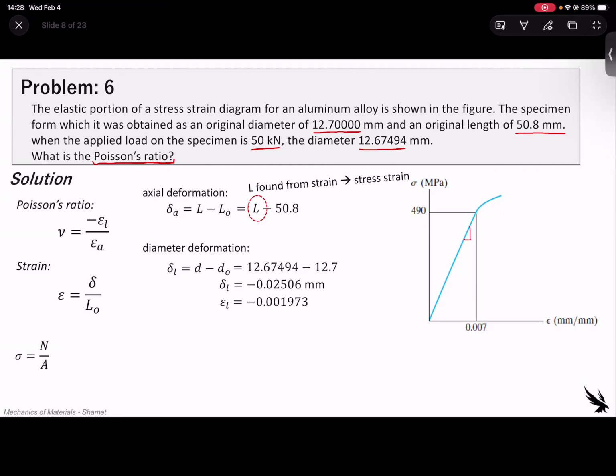And we know that the stress on this y-axis is the internal force divided by the cross-sectional area. We're told that the internal force is 50 kilonewtons. So 50 kilonewtons, or 50,000 newtons, divided by the cross-sectional area is producing a stress of this crazy looking number. We're just going to simplify this to 394.7 megapascals. Now, why megapascals? Because that's what this is currently showing in. So we know that it would be somewhere around here. It's not to scale. You're not going to have to scale it.